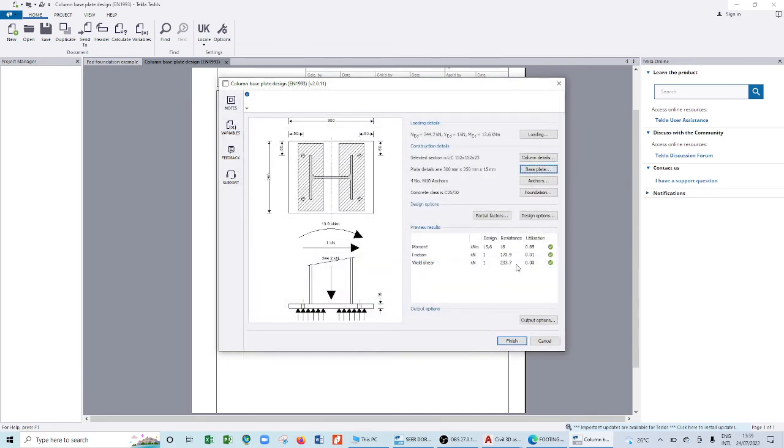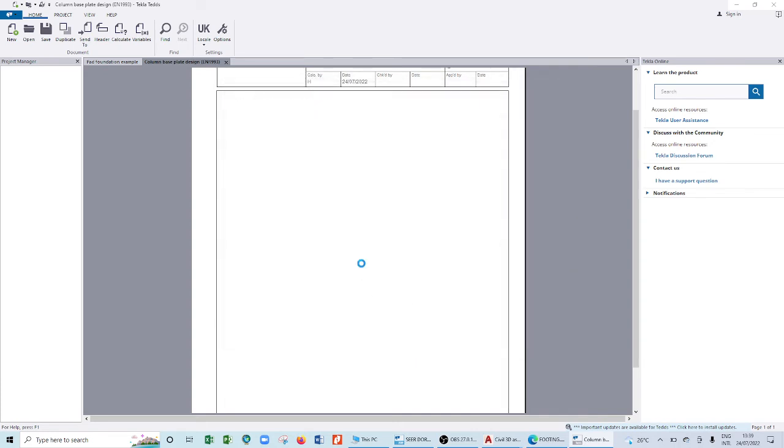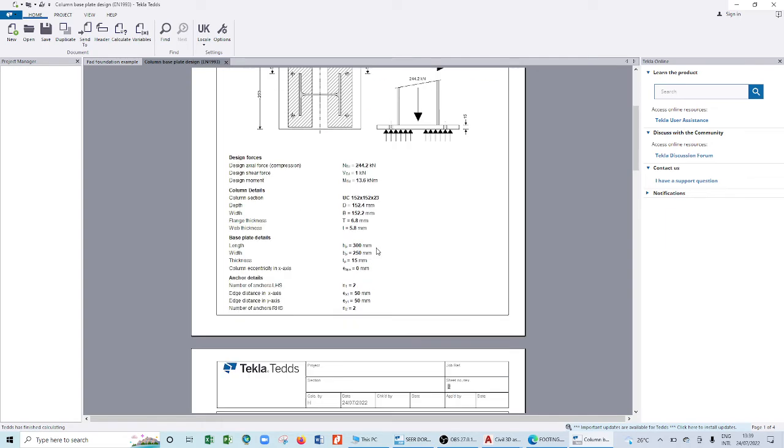You see what has happened when you change to 15? Reason being, the plate would fail if you leave it at 4 thickness. Because of the moment, the plate will either tear off from this other side of the bolt and this other side will break off into two. So now, by adjusting that, I see that the utilization we have is 0.85. So we have actually utilized 85%. Then you press finish. So this is what you have in your design of the base plate.